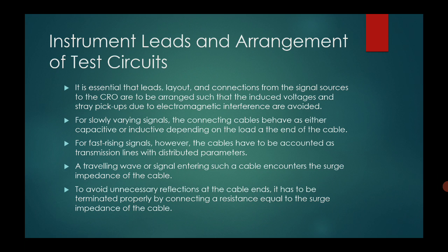For slowly varying signals, the connecting cables behave as either capacitive or inductive, depending on the load at the end of the cable. For fast rising signals, however, the cables have to be treated as transmission lines with distributed parameters. A traveling wave or signal entering such cables encounters the surge impedance of the cable.